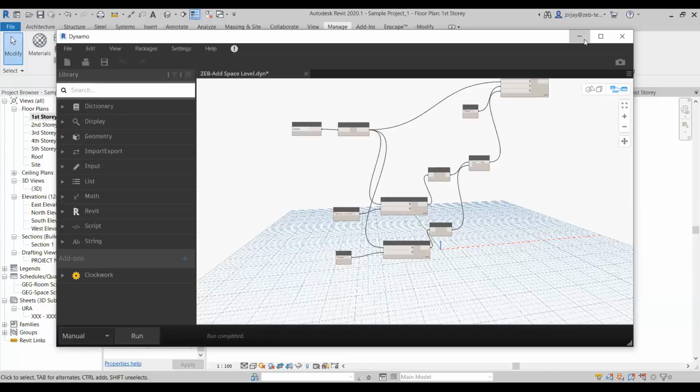The ground plane should be the first story. And in this case, we use spaces instead of rooms. So we're going to choose spaces. And by right, you should see that it will turn green here. For all these other options, you just choose the default.